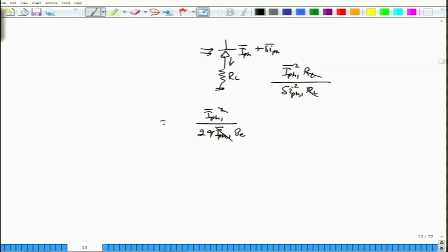So, you see that the SNR is actually proportional to the current that you are generating in the photodiode, and of course, this current is proportional to the optical power that is launched when you send a bit 1. So the only way to increase the signal to noise ratio is to raise the input signal power, so that the current rises, and therefore the shot noise, although it rises, rises only by a square root, and therefore you are saved by this mechanism. So, to reduce the BER, you can increase this.